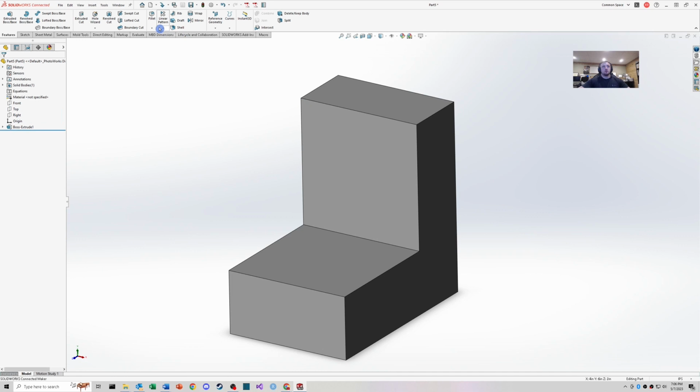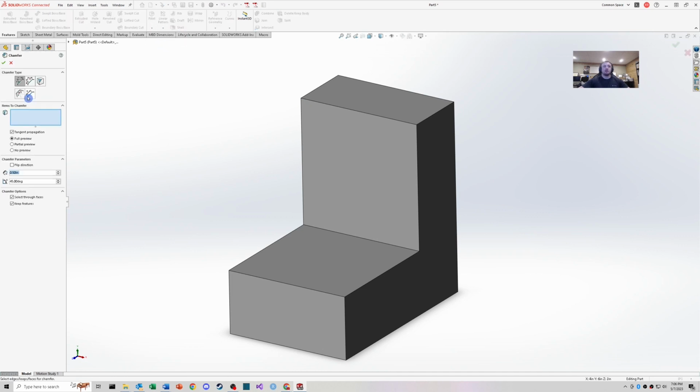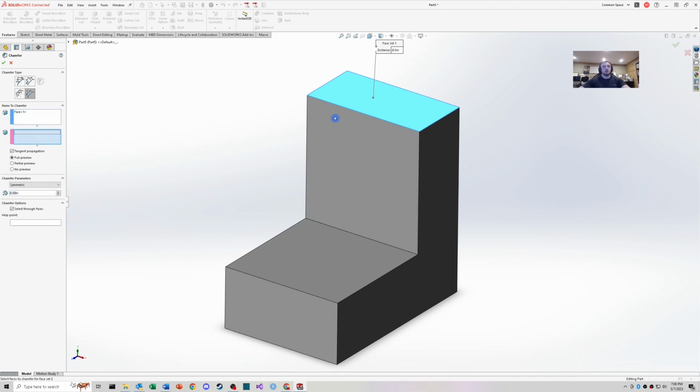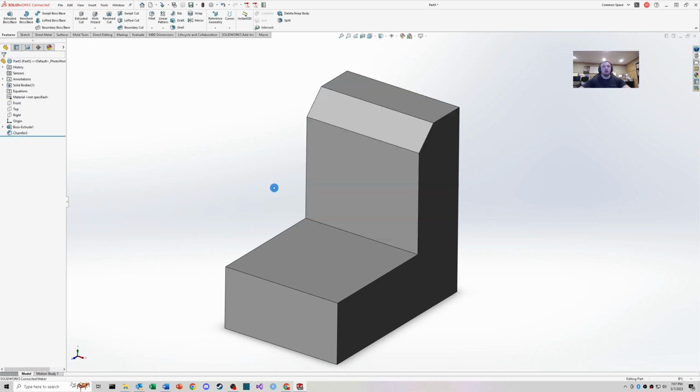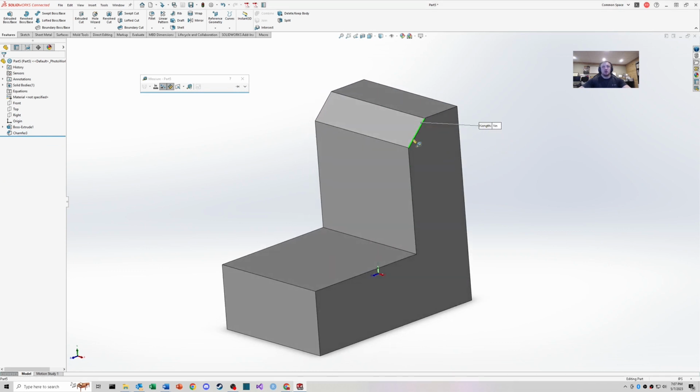Let's close that and start a new chamfer again. If I wanted to define the straight line distance of the chamfer, I can select this type of chamfer. Sorry, actually I would select the first face and the second face of that chamfer. This gives me the opportunity to select chord width or hold line, which I'm not familiar with. I'll have to look into that more, but chord width will allow you to input the straight line distance of that chamfer. If I create that chamfer like that, and then use the measuring tool to measure it, it's actually 1 inch as a straight line distance.